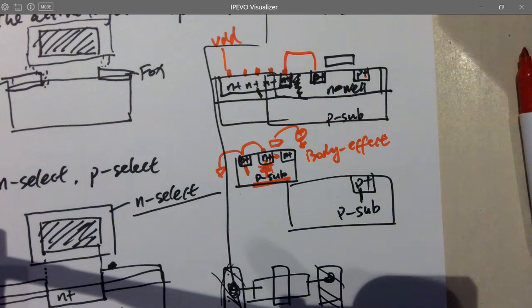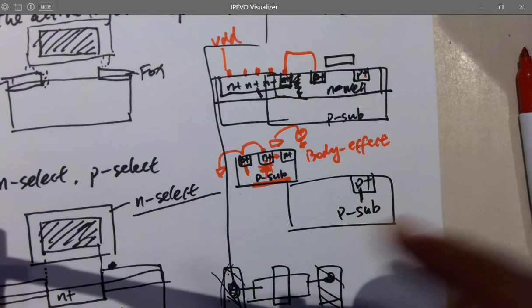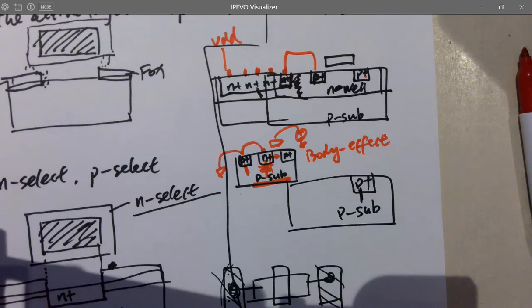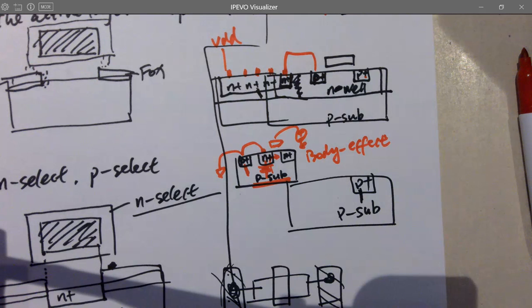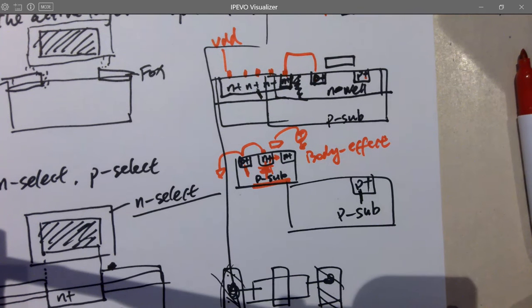The solder material only attaches to metal when it's hot. So that's why you have very tiny metal pads on the PCB board, and the pads are very close to each other, and you just dump solder material to the pad, and it just stays on the pad instead of shorting all the neighboring pads. Why? Because whenever the solder is being melted, it only stays on the hot metal, not the fabric material, the PCB. Not to mention the wafer, it's silicon.